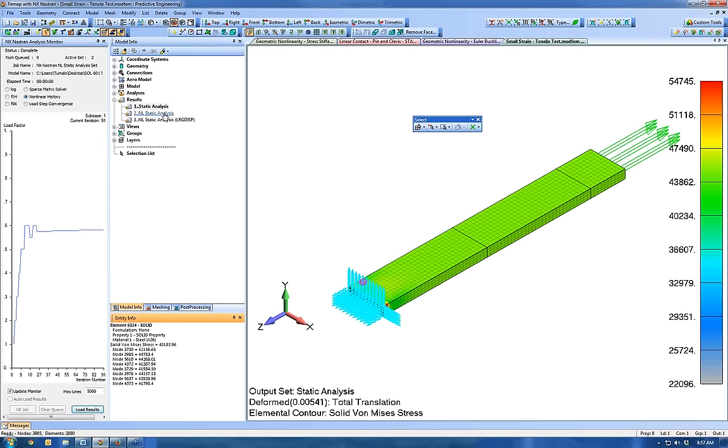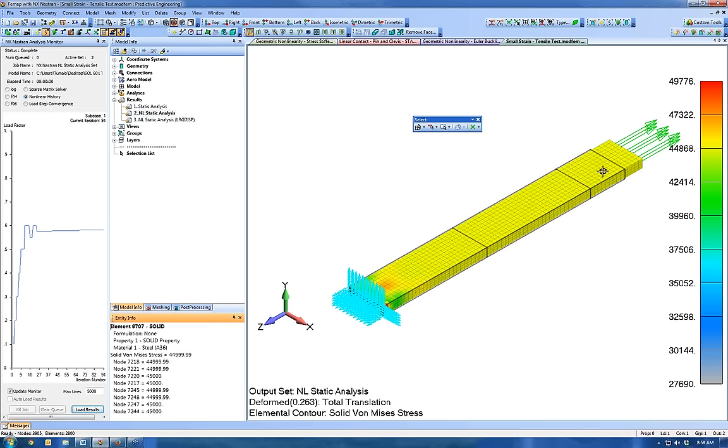Now if I switch over to a nonlinear analysis, I've got plasticity. You can see this thing narrowing out here between the linear and the nonlinear. In the nonlinear, we're getting more elongation, and our cross-sectional area is reducing even more. But if you look down here in the entity info, our nominal stress value is still sitting at 45 KSI.